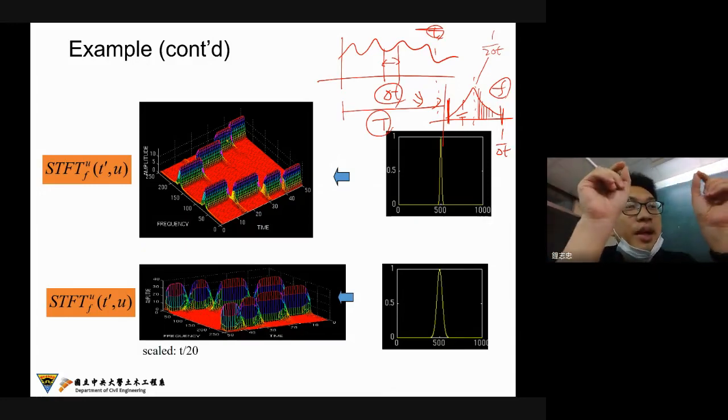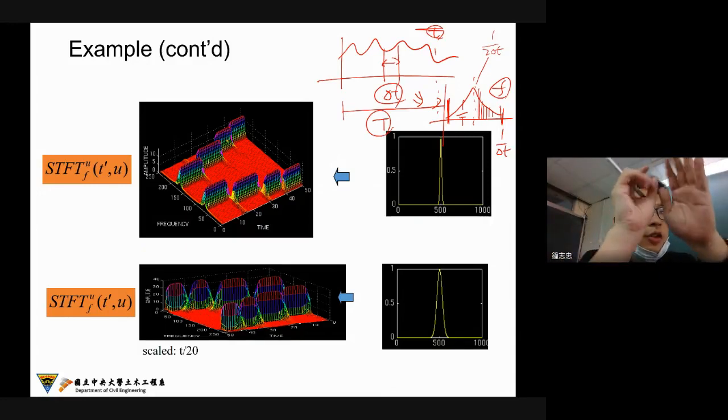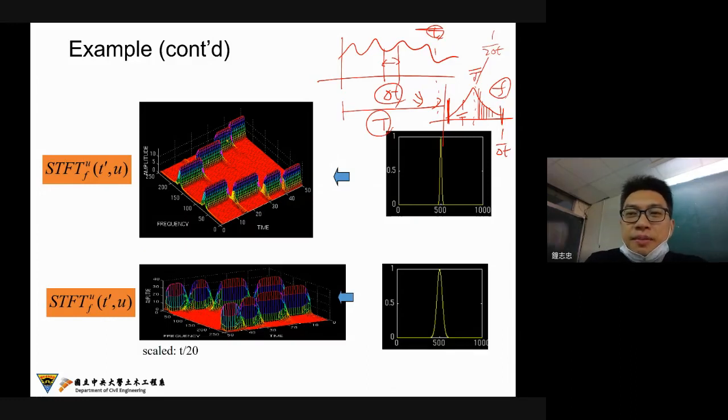In the frequency domain, the frequency spacing between the data is the inverse of the big T. So I would like to conclude that the window of the truncation controls the resolution in the frequency domain, and the resolution in the time domain controls the maximum frequency in the frequency domain.